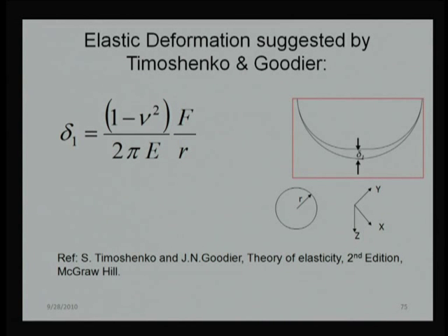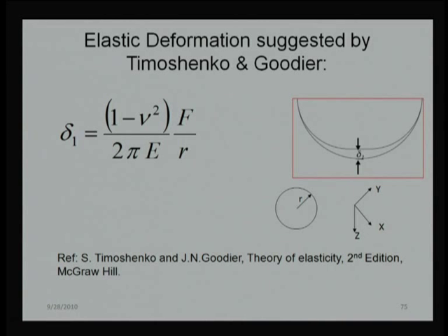Now, why are we emphasizing the pressure? Because when we discuss hydrodynamic lubrication, we have not discussed in terms of force, we have discussed in terms of pressure distribution. So, we will know the pressure distribution after solving the hydrodynamic equation. However, if we do not require hydrodynamic and only require simple elastic deformation, then we can treat F directly. We do not have to come to the pressure. Well, we require elastic deformation to be joined with hydrodynamic lubrication. That is why we are talking about the pressure term, and giving the explanation in terms of pressure.